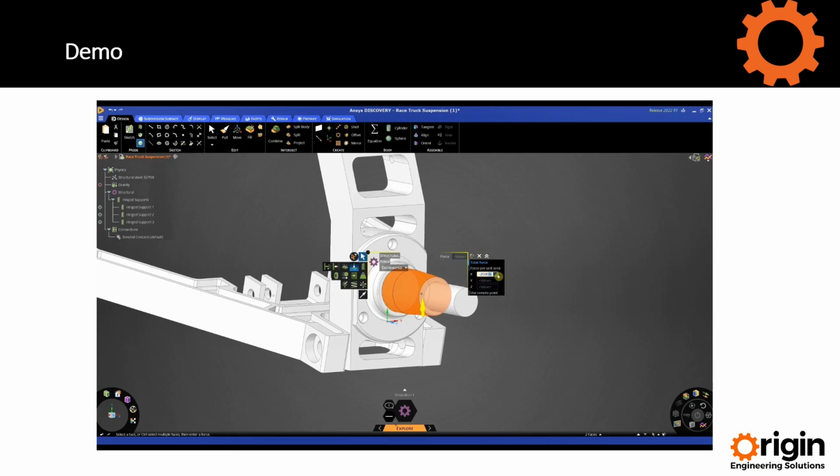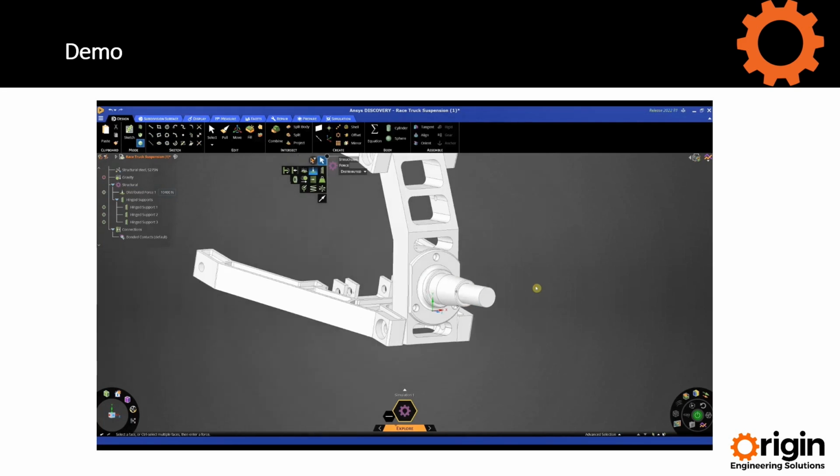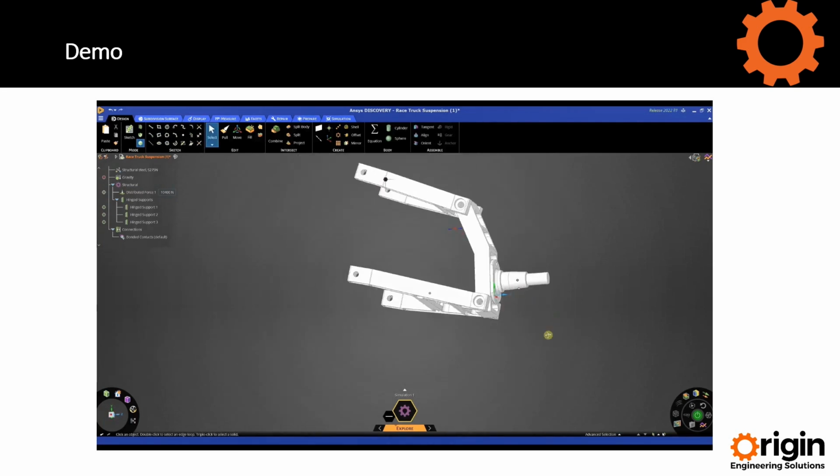So I'm going to apply a negative 2000 in the X direction, or minus X. I'm going to apply a positive 10,000 in the Y direction, and let's do a negative 2000 in the Z. So you can see you can apply these any way we want, or we can use a remote point. Once happy with it, let's just hit the escape key a couple of times, and now we can see our force has been set.